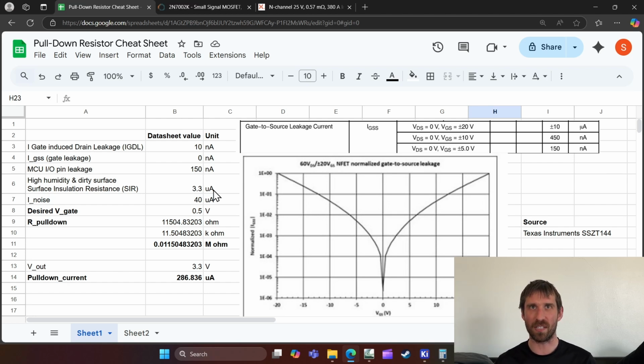This is why your ICs, when they're packaged, it's low humidity. And they'll give you humidity specs, like when you open this package, you've got 30 days to put it on or something like that. So I would encourage you to look this up. This is a way bigger deal than I ever thought. Like, I was never taught this. But we're going to use pretty much worst case here. So noise, this is a crap ton, but I just did this to get close to 10K as kind of a what if. Like, this is nuts. That's a lot.